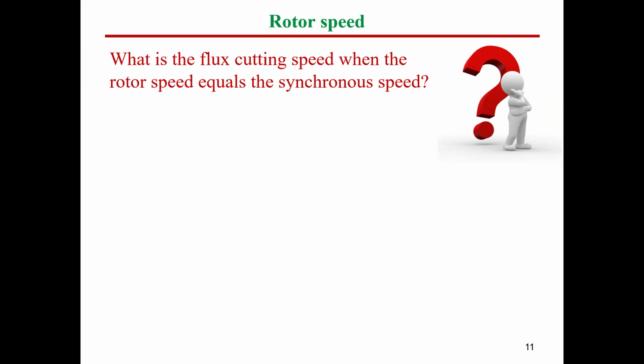You know that the speed of the rotating flux is nothing but ns. Since the supply has frequency f, we expect the synchronous speed to be 120 times f divided by the number of poles of the machine. This is the synchronous speed, the same as the speed of the flux coming from the stator side.